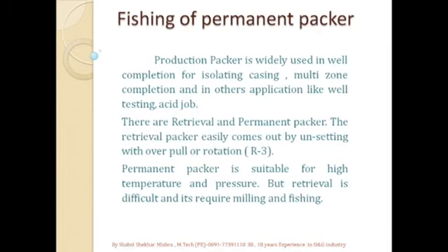Mainly in well testing and acid jobs, we use a mechanical packer, which can be set and unset multiple times at the desired depth. So there are two types of packers based on the type of setting and retrieval. One packer can be retrieved, and another cannot be retrieved simply by pull.